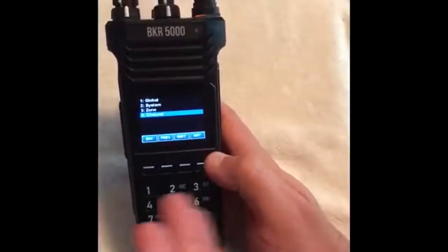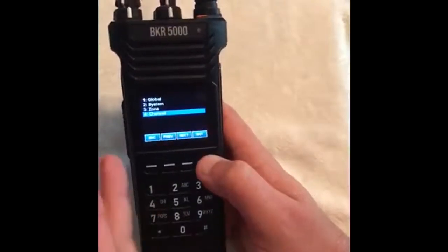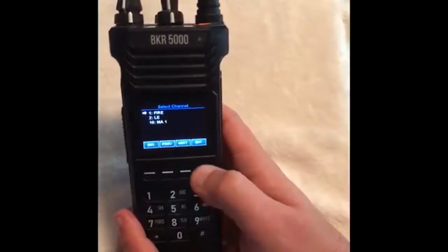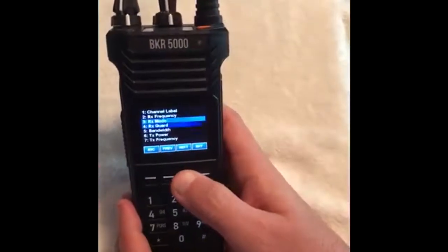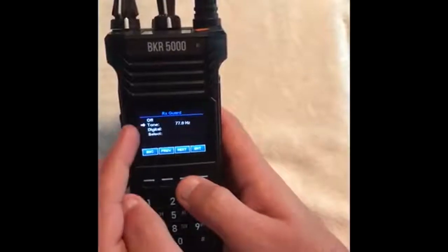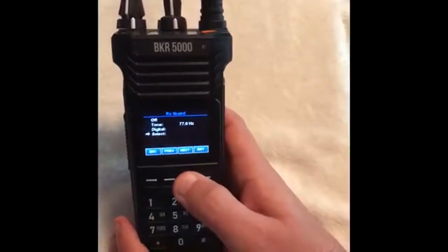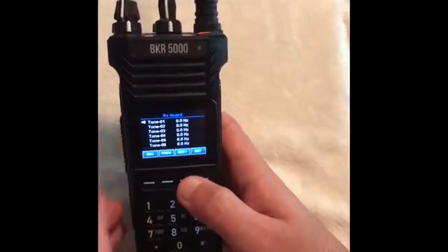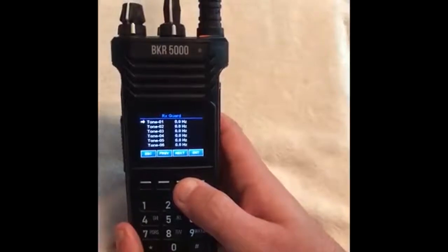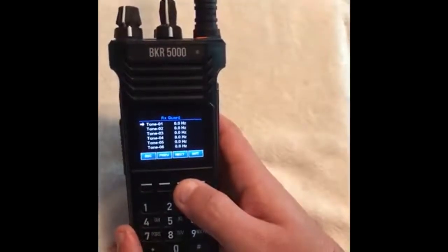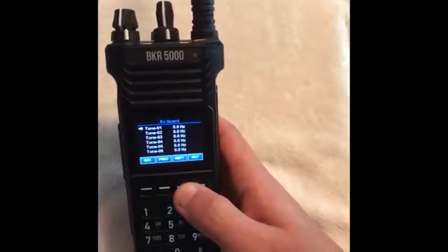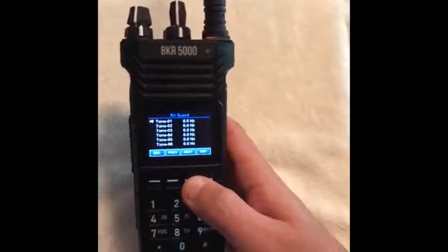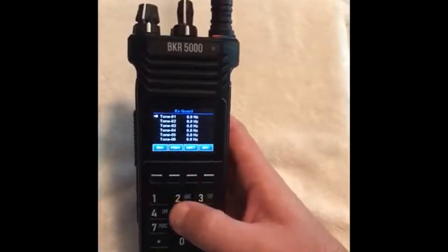So for this particular radio, I don't have a pick list, but let's go to channel and then edit channel. And we'll edit the fire channel. And then when I go to RX Code Guard, here you see I have tone, digital, or select. If I go to select, this then brings me to my Code Guard pick list that I can pick from that's already programmed into the radio. And they can select from there. And then if after the fact they need to change it on the fly, they should still be able to go through the same process they use to change their Code Guard from a pick list.